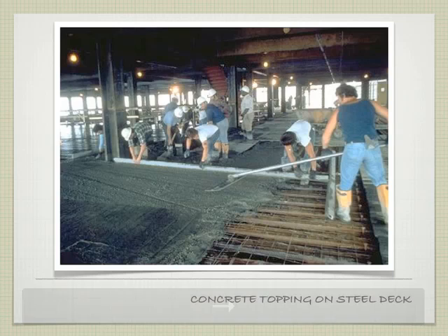So, just like when we pour concrete on a concrete building, if we're pouring concrete on a steel building to make this topping, we go through basically all the same steps that we talked about. So this is a good review for us anyway. But if we look down here at the area that hasn't been covered with concrete yet, we have our corrugated decking, we have our row of shear studs in place. So that's good. The other thing is they put a layer of welded wire reinforcing, the WWR, inside this, and they're treating it just like a slab on grade, or a slab up higher in a building. It's the same concept.